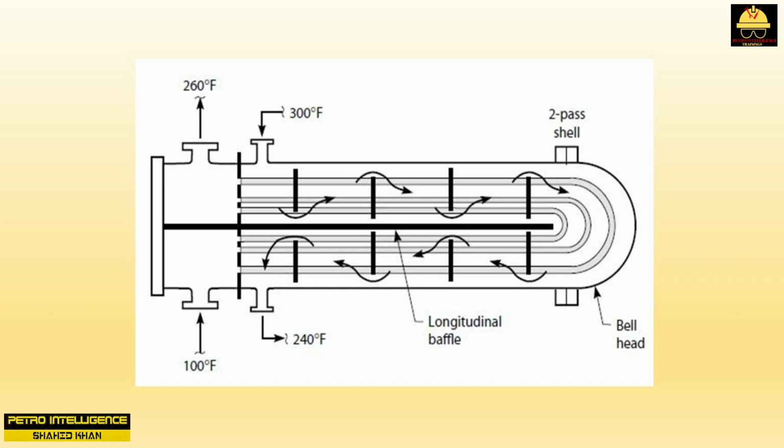Such an exchanger is truly countercurrent. The engineer does not apply the F-factor derating coefficient to the log mean temperature driving force, as would normally be used for non-true countercurrent flow. This would make it seem that the two-pass shell configuration is inherently more efficient than the ordinary single-pass shell exchanger. And it is, in theory. Then why do we see so few of these exchangers in service?